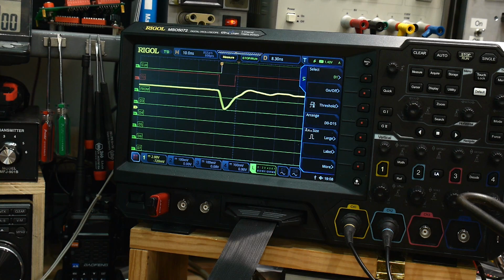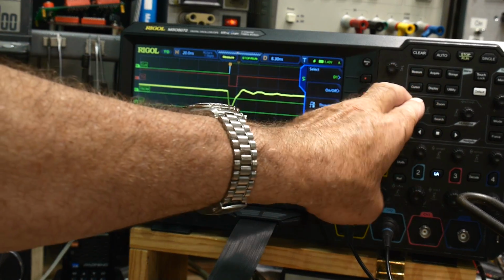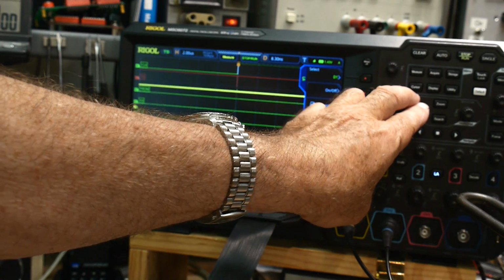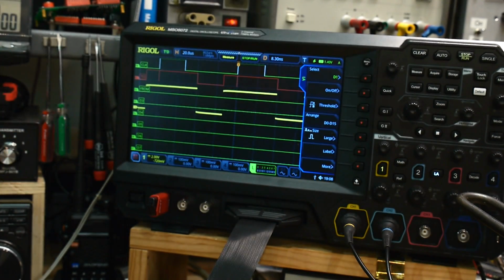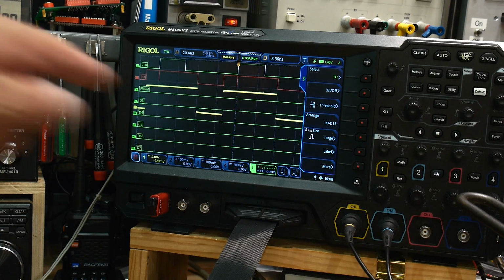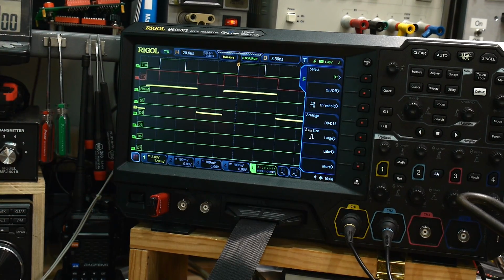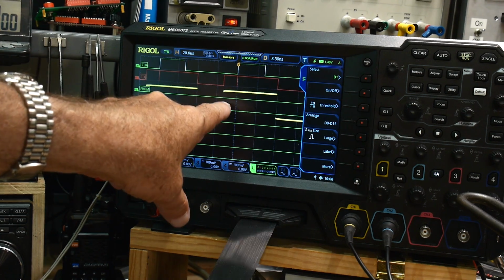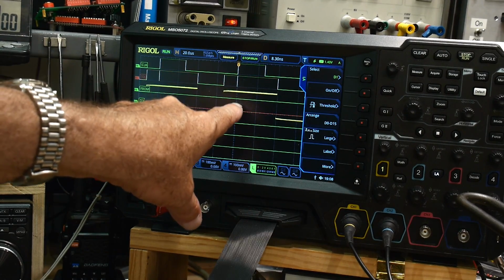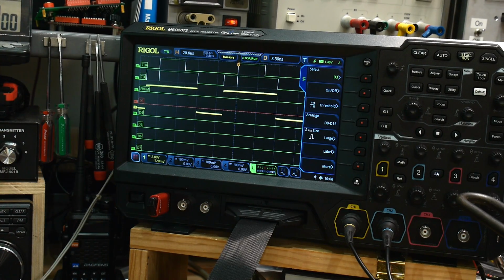I think it has to do with the programming of the GAL. I might have to take a look at how I actually program that part and see if there's some condition that creates that little glitch there, and if I can get rid of it. So if we zoom way out back to where it's normally operating, and we didn't have this logic analyzer, we would never know there was a pulse right in there. In fact, how would we even know to go look for it? How would we know to trigger on it? Because these are the edges that we can trigger on when we have an analog signal, but how do we go way in there at 10 nanoseconds per division and find that little pulse? You just can't. It's an impossible task. So that's where logic analyzers and mixed signal scopes come in really handy.